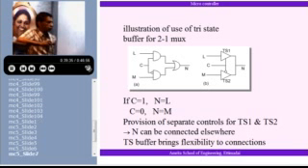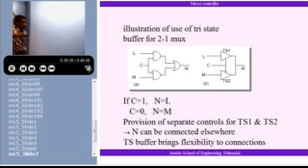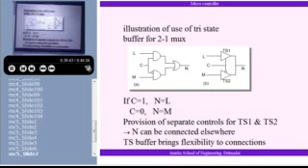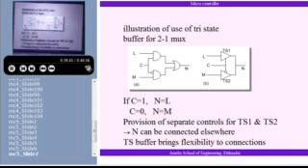I am showing how I can make use of the tri-state buffer. See here, this represents the 2-to-1 mux that we discussed earlier. One signal, another signal. This is a control signal. If it is high, this is completely off. This is 0, this AND gate is off. This output is steered to this. So with 2 AND gates and this OR gate, I get a 2-to-1 multiplexer.